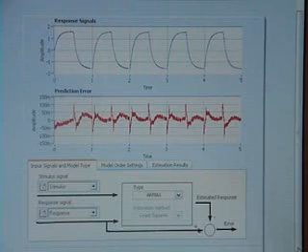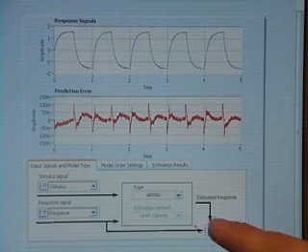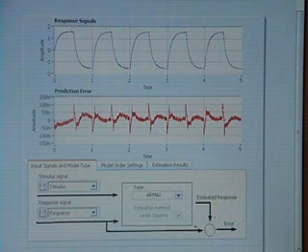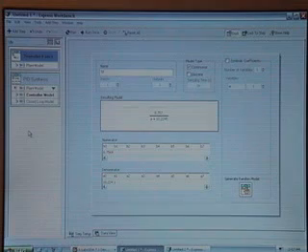Okay, so here we're showing the system identification software, which will allow us to create a model for our DC motor. So it takes the incoming step response signal and allows us to vary the type of estimation that we're going to use. We can change the different orders for the coefficients, and the result of this process, of course, is an actual transfer function that we can use to model that system. The next step is to do the control design.